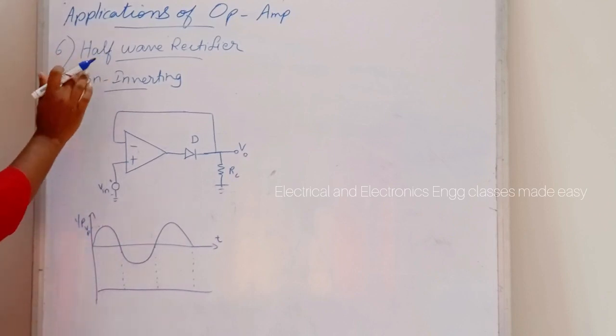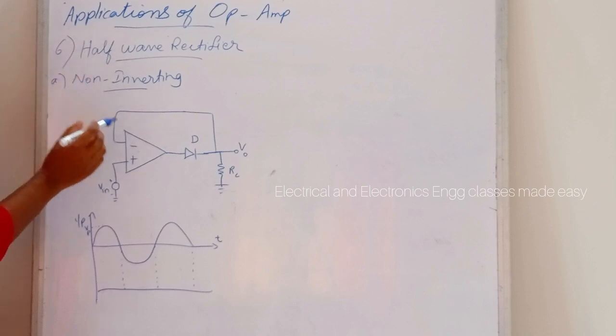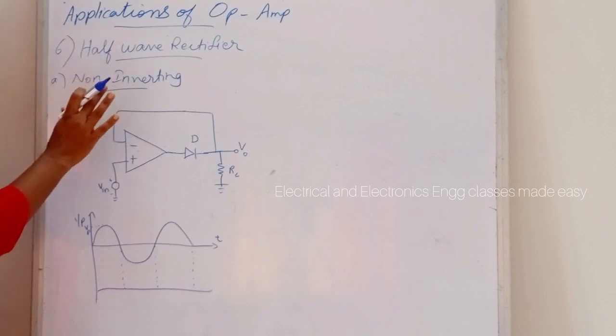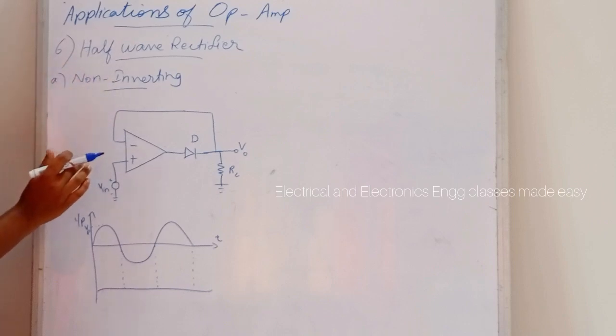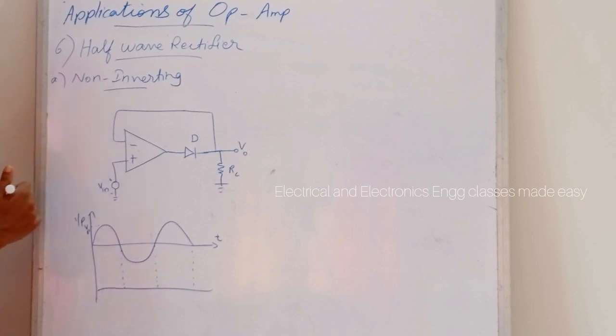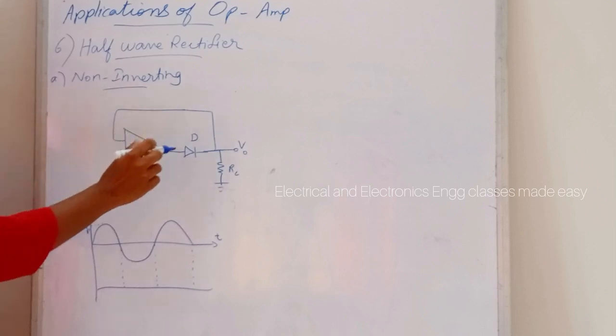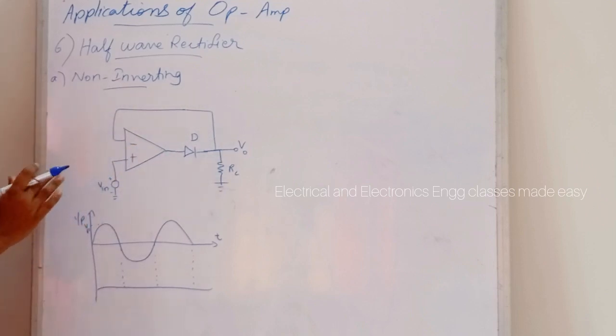The op-amps can enhance the performance of the diode circuits. An op-amp eliminates the effect of diode voltage drop, allowing us to rectify, peak detect, clip and clamp low level signals. Here is the circuit for the active half-wave rectifier circuit.